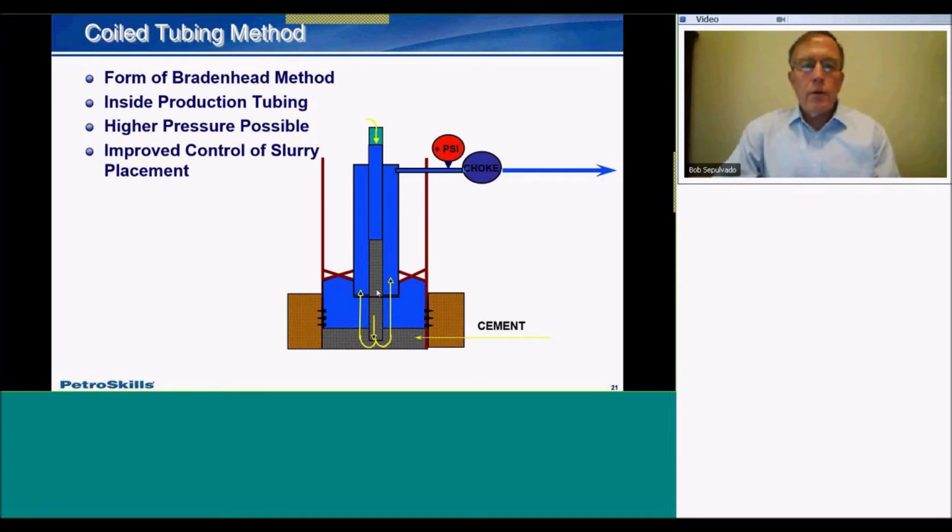Some operational concerns with regard to the coil. Say, for example, you're working 3,000 feet from surface, vertical, and you have 10 to 15,000 feet of coil on the unit. You cannot simply isolate 3,000 feet and pump through it. You have to pump through the entire reel length on the unit. And since the ID is very small, you cannot pump at a very high rate. So you're limited with rate. So additional concern needs to be looked at with regard to the slurry design itself.